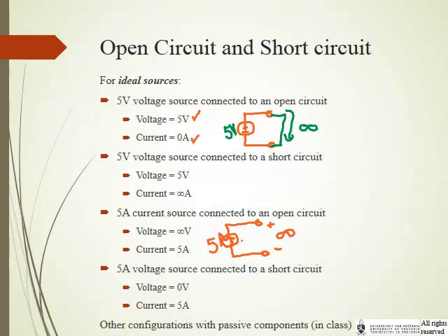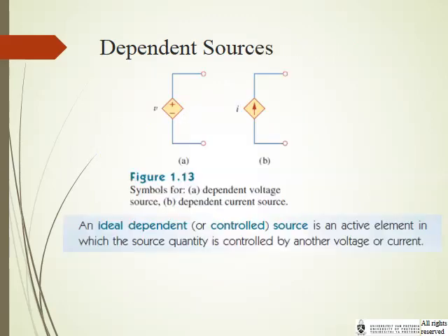But what if we do a short circuit, and now we short circuit a different color, that one. So now we put a short circuit across this. What's going to happen now? Now the current can flow freely through the short circuit, and that means that for a short circuit the voltage drop is going to be 0 volts. So that was independent constant sources.